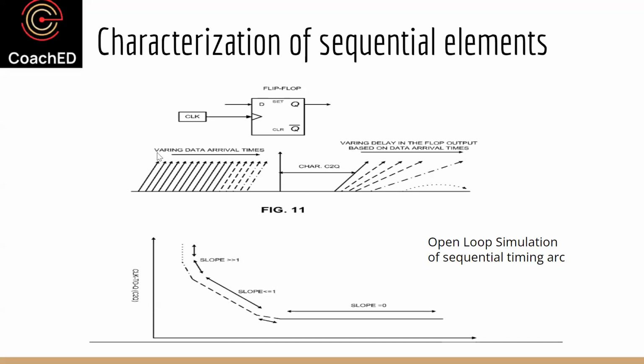So for a long time, for a lot of values where data is coming early compared to the clock, the output value is fixed, not changing. Notice this relationship between the arrows. The bold arrows, this clock to Q. And for dotted arrows, you have these behaviors. And then for these ones, you start having some failure. The data does not get captured at all in the flop. Output does not change. So this is exactly what is also shown in this plot here.